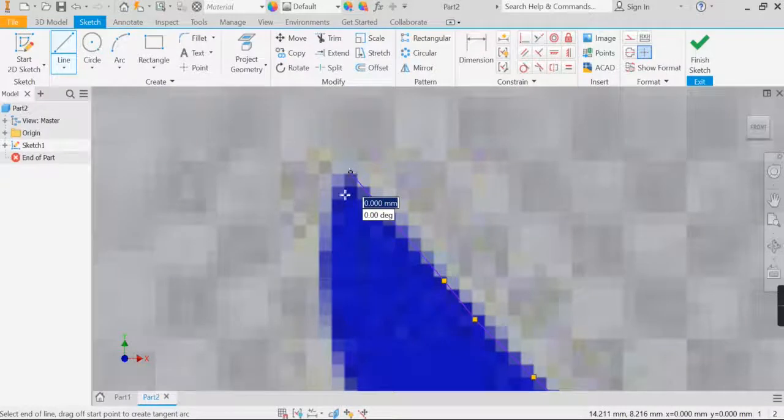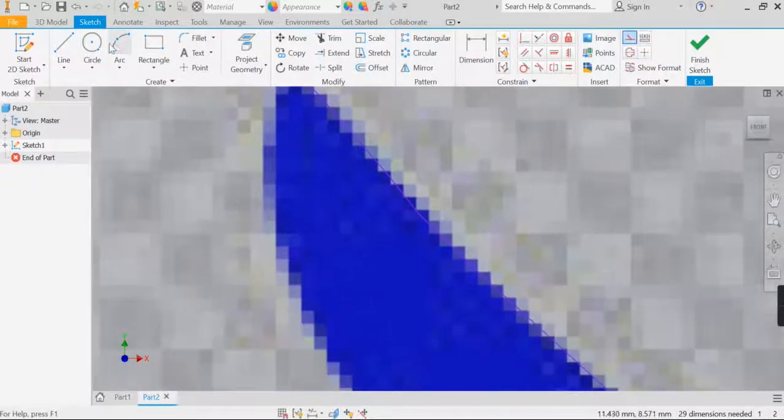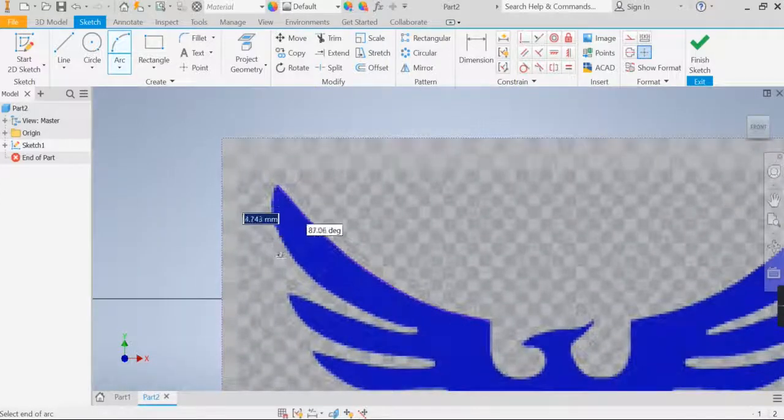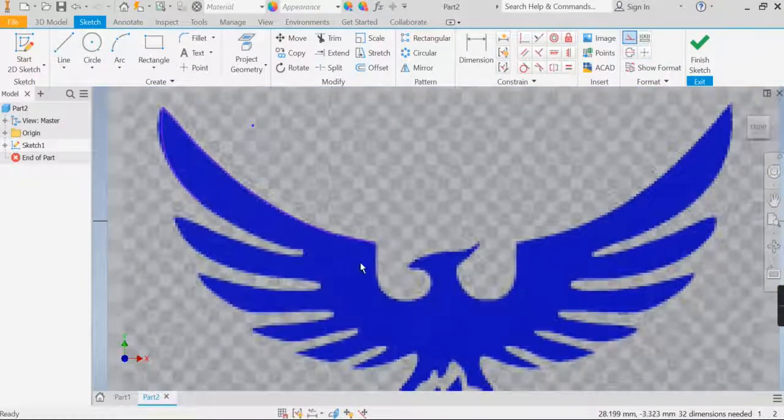So this is one way of doing it. Grab and drag. Another method is, for instance, because there's a curve here, I can use my 3-point arc tool, find that green snap node, and find the start and end of that curve. I'm going to roughly guess about here, and trace that as best you can, always making sure you have that snap node. If it's yellow, that won't work.